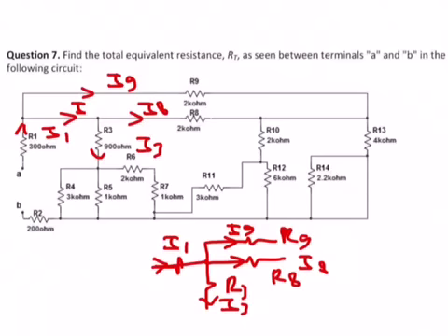So now the things will start to shape. I can see that I'm going to redraw the circuit. I will make this node the same as this node. I will make this node the same as this node, and I'm going to redraw the circuit again. And you'll see the circuit is way simpler than it looks originally, and the R14 will disappear because R14 has been shorted out.